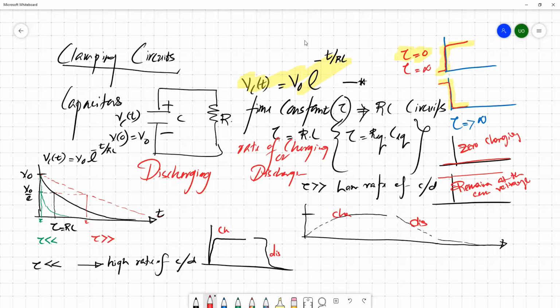Okay. So again, for practical circuits, we found that for this charging and discharging process, the capacitor needs 5 times the time constant to charge or discharge to its max or min. So it means we know the time constant is somewhere here.